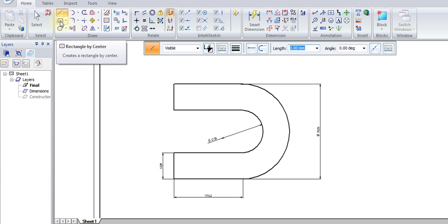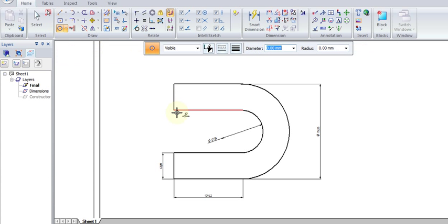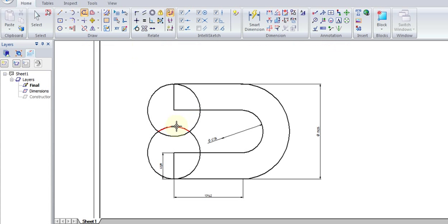Okay, so we're in the final layer. Let's actually add a bit more geometry. Let's put one circle here, and let's do the same thing here. And let's just use trim and get rid of those. There we go. And let's get rid of these two. Now we deleted the dimension that was there, but we know that that dimension would have been deleted because there's nothing to reference. Now while we deleted that, as long as the dimension needed to reference some material, it will be deleted automatically from the Dimensions tab as well.